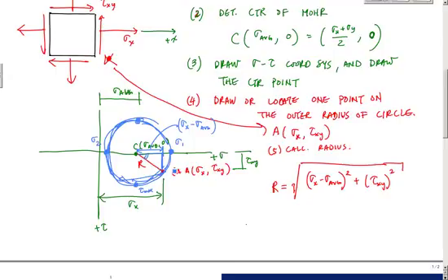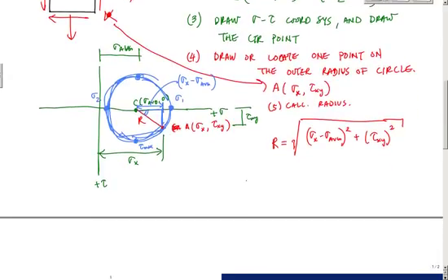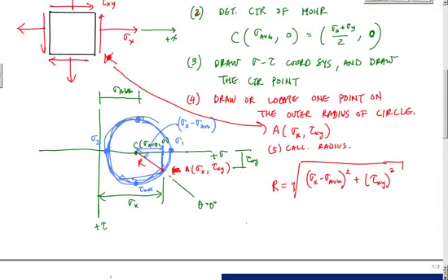And once you know this, the nice thing is that when I look at this circle, this line represents theta equals 0 degrees, or this original coordinate system. If I want to get to my maximum principal stresses, I go this angle right here in Mohr's circle. If I rotate counterclockwise in Mohr's circle, then I rotate my state of stress counterclockwise, and that's going to give me a second state of principal stress there.